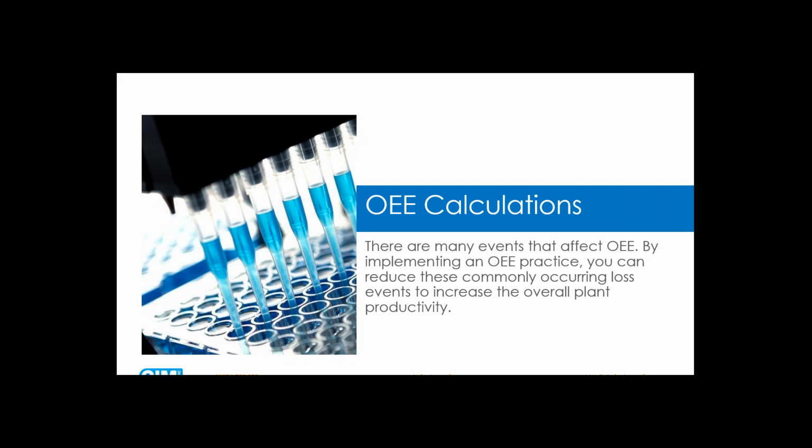Some people would call OEE of a line OLE rather than OEE, and some people might consider OEE of a machine to be a slightly false indication because the speed that machine 1 on the line can run at is impacted by the speed that machine 2 is running at. So it can give you false readings. It's important to take a wider view. And what the goal is, what are we trying to do? We're trying to get more product out of the door and work back your individual calculation from there.